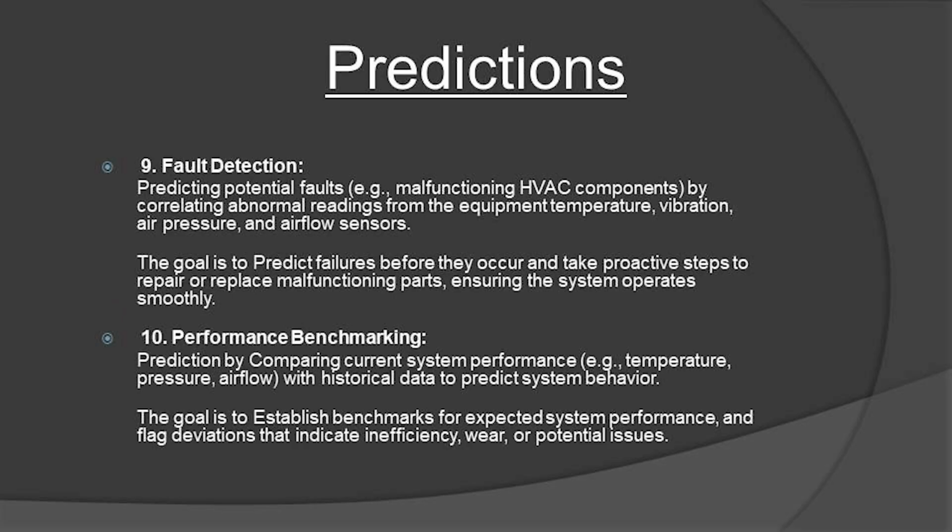Fault detection. Predicting potential faults, like malfunctioning HVAC components, by correlating abnormal readings from the equipment temperature, vibration, air pressure, and airflow sensors. The goal is to predict failures before they occur and take proactive steps to repair or replace malfunctioning parts, ensuring the system operates smoothly.